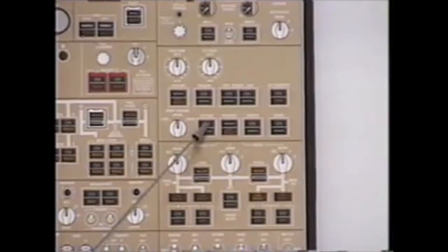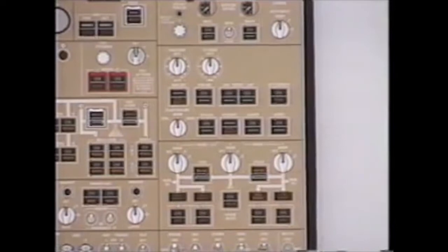High flow, if we press this selection, the packs are in high flow. Humidifier, the flight deck and flight deck crew rest areas only are humidified. No other sections of the airplane are humidified. The humidifier takes water from the potable water system to humidify those areas. The captain will select the humidifier to on during the cockpit setup.